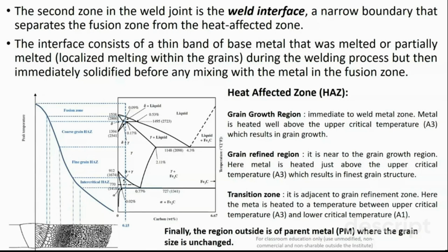If you remember, there are three terms in this particular section: first the recovery, second the recrystallization, and third the grain growth phase. In the recovery phase, if you apply heat, the dislocations inside the grains rearrange themselves and produce a strain-free region. That strain-free region gives the sites for the nucleation of small grains. So this is the region where the recovery starts.